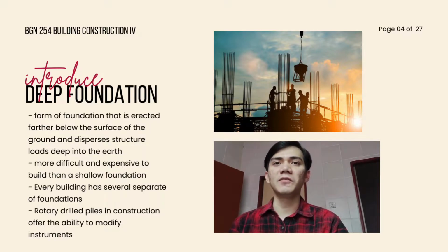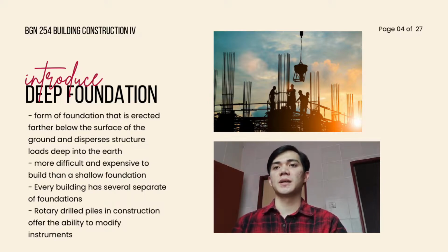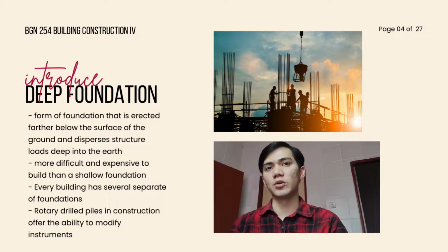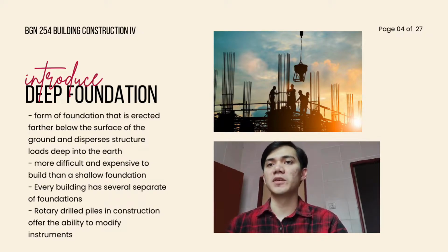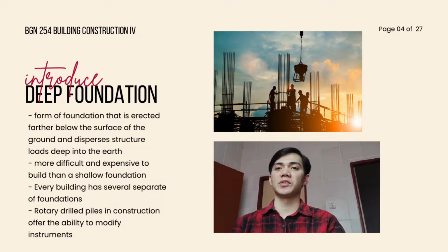However, a deep foundation is likely to be the best choice when coping with poor soil conditions at shallow depths, significant design loads, and site limitations. Every building often has several spread foundations. It is to ensure that the column weights are passed to the ground directly. Deep foundations also provide advantages over shallow ones, being appropriate for challenging soil conditions and having fewer site restrictions.